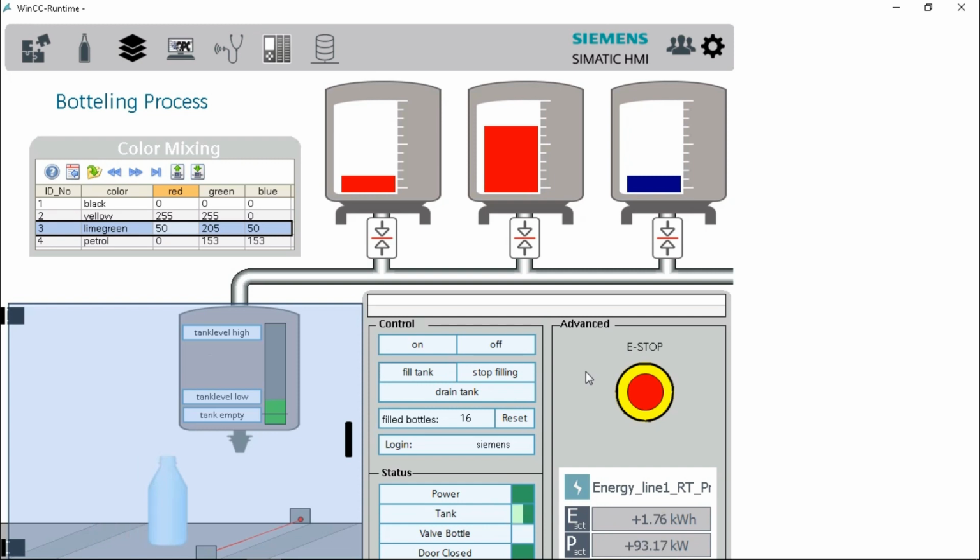my valve state here. So I choose exactly that tag, that structure element under my UDT and tank info, and because it's tank red, it would only make sense to use my tank red UDT. And now I see my structure instance is linked to my valve state. And then in the faceplate itself, again, it connects or links the structure instance to the elements there. So basically the same functionality as in WinCC 7.5.